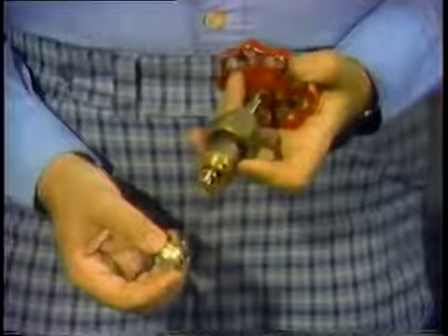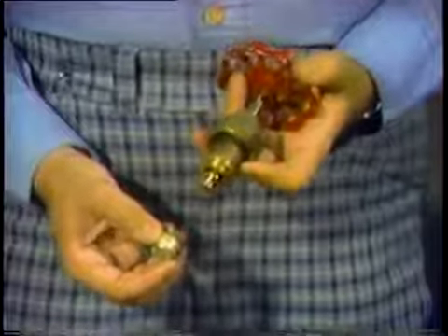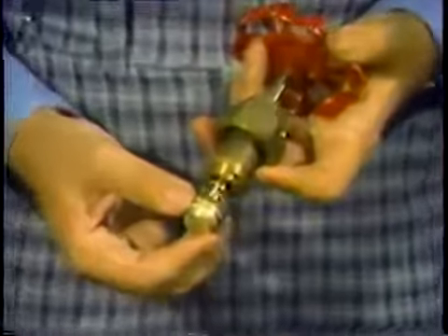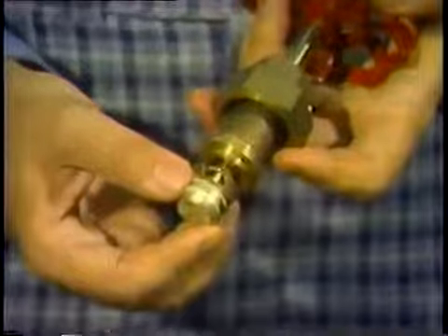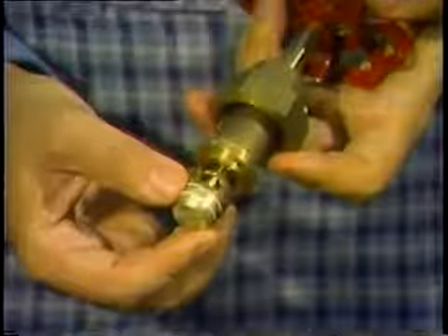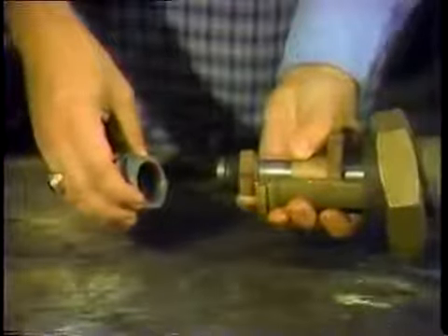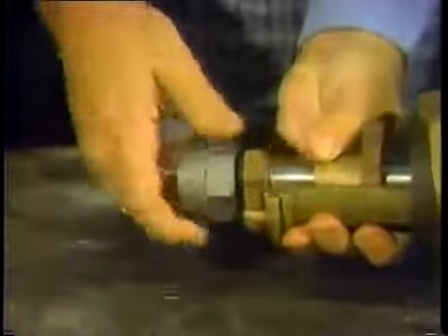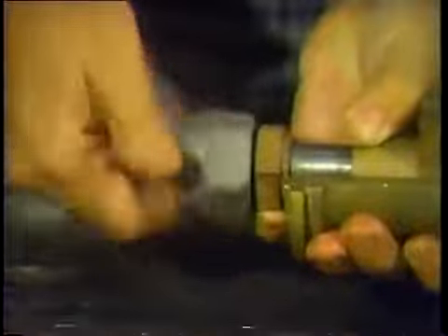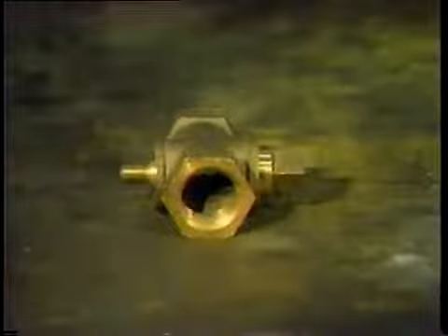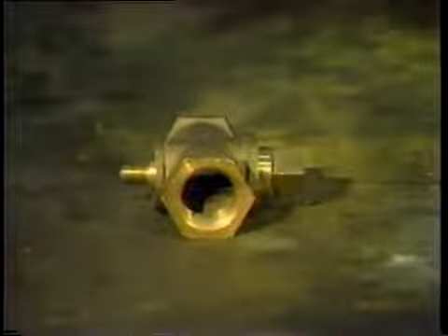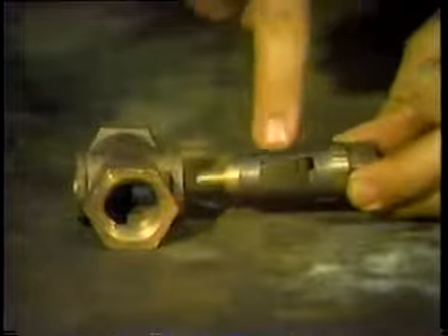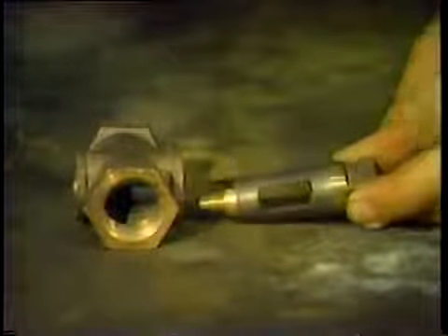There are several ways to attach the disc to the stem of a valve. One way is called the slip type joint. The disc slips over the end of the stem, and the valve body will prevent the disc from slipping off the stem. Another method of attaching the disc to the stem is threading. The disc is threaded onto the stem like this. Some discs and stems found on inexpensive low-pressure, low-temperature valves are manufactured as one piece and cannot be disconnected.